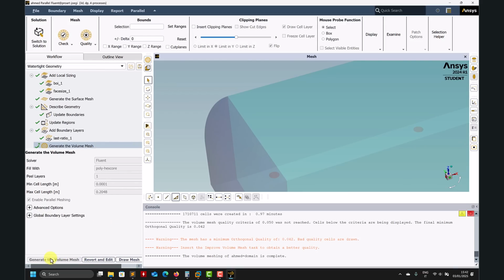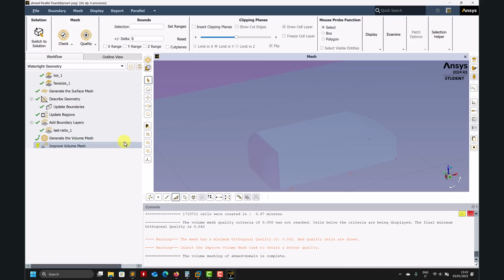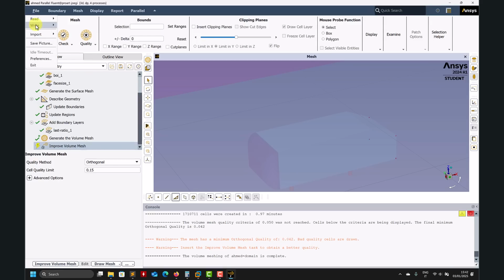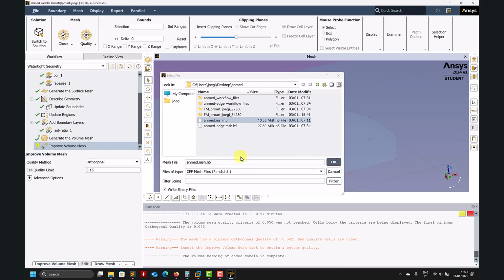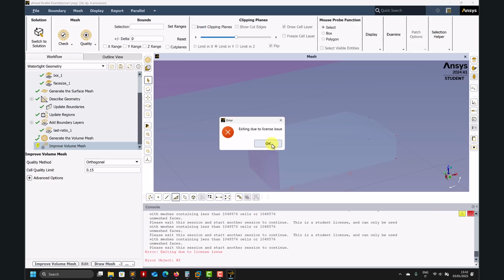Okay, so we have solutions. We have a couple of bad quality cells. You'll see that you mark those cells there, but in general, you can see that by refining the mesh, you solve the other issues, aspect ratio and so on. So you can get the idea, similar to Snappy. Let me add here improve mesh before doing so, because in my experience, sometimes it will crash there.